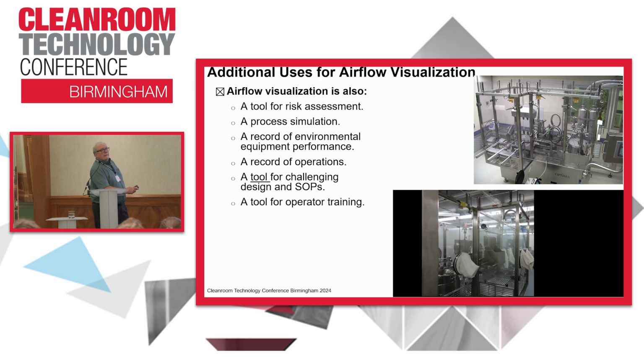And again, the filters in the ceiling were not coupled to the enclosure, and that can be problematic, as you can see in the videos. Long story short, 2 years after we did the studies, the company had pulled out the brand new filling machine, redid the clean room and put in an isolator. They never were able to get that line up and running.